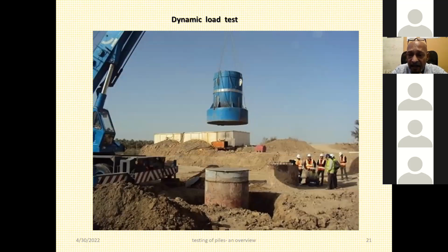Then the third test is a dynamic load test. In the dynamic load test, quite a heavy hammer is dropped on the pile. This pile cap requires a very good kind of preparation so that it should not get shattered. It requires a MS cap, extra concreting, then there is a MS plate on that to take the blow. There is some cushioning also provided, which affects the efficiency of the hammer, which Mr. Shekhar Vaishampayan has spoken about in the formula.